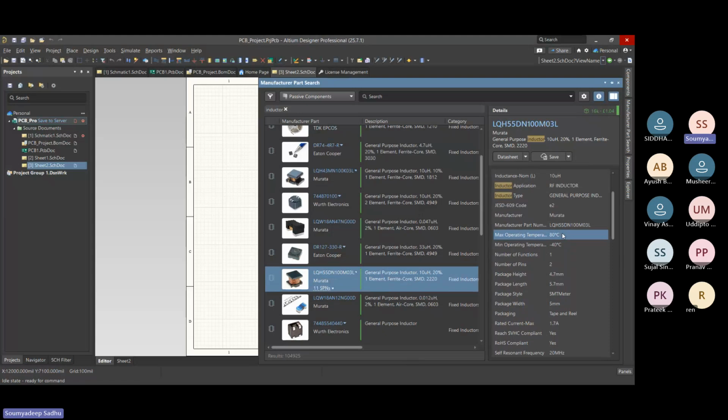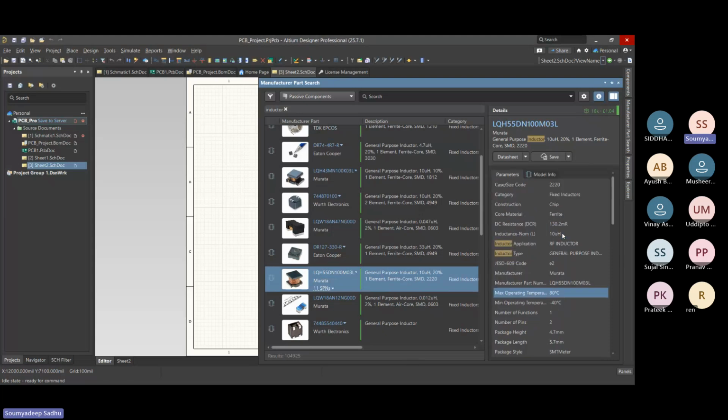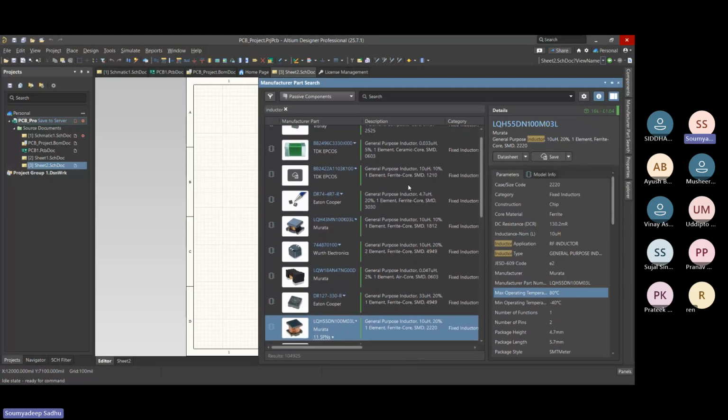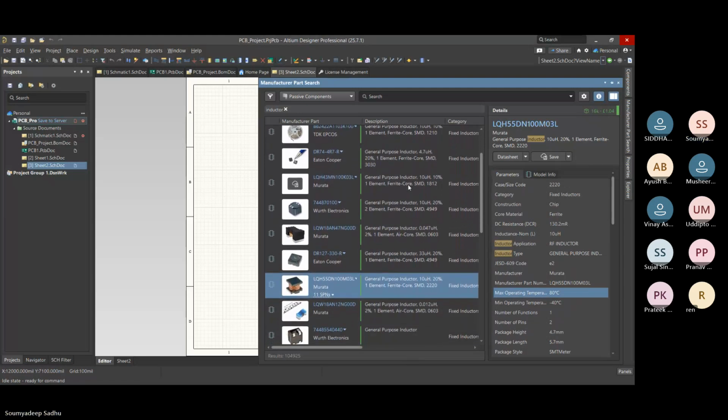Especially power converter modules, because they are using high frequency conversion. They have high current input or high voltage input, and frequent switching of MOSFETs or transfer of energy from one energy storing component to another may lead to heating up of the wire in between them.